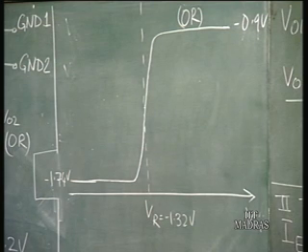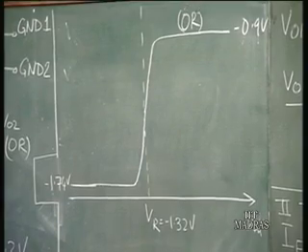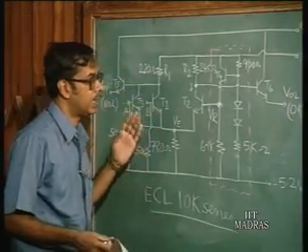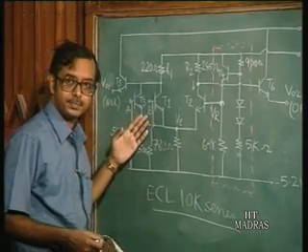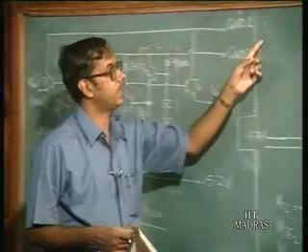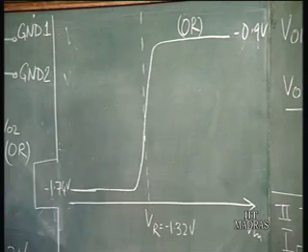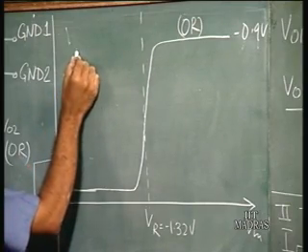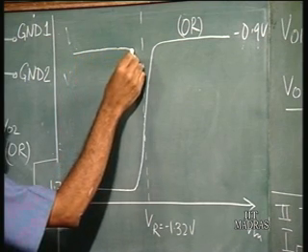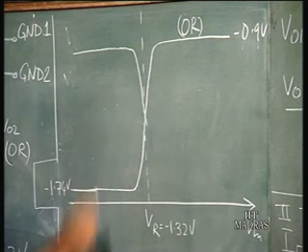All right. So, it goes from minus 1.74 to minus 0.9 volts. What about the NOR? NOR voltage, so basically in the case of NOR output, again when the input is low, the output is going to be high. Okay. So, here the output is going to be high. All right. So, what is the value here we have seen? Again minus 0.9 volts, and then it goes like this.